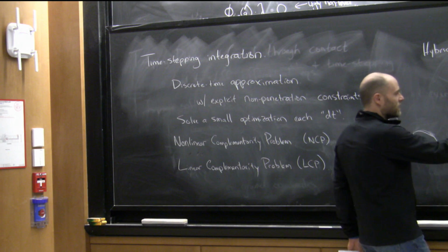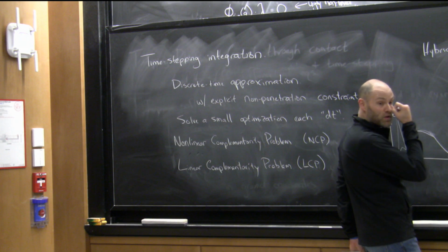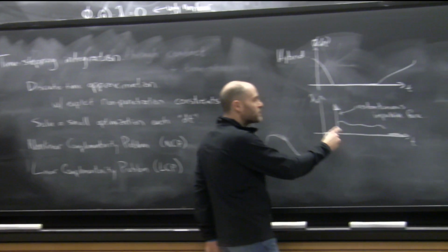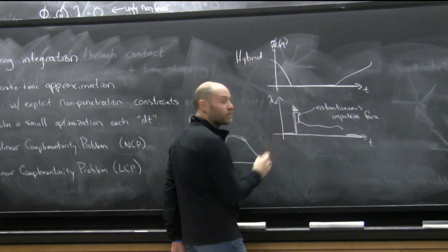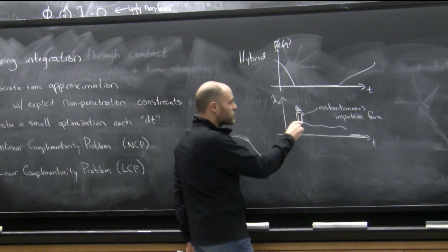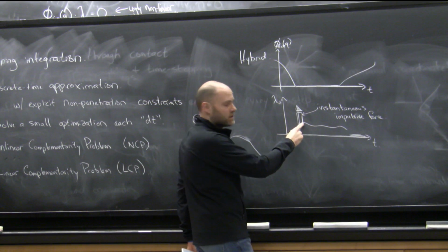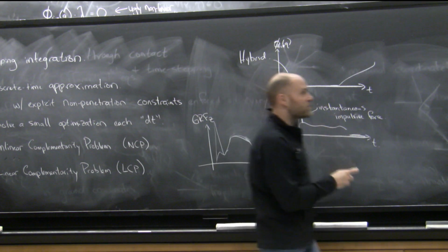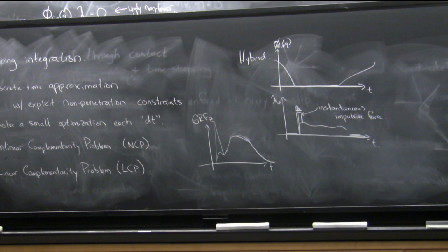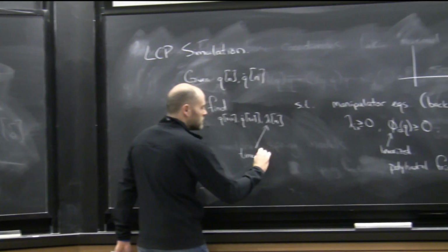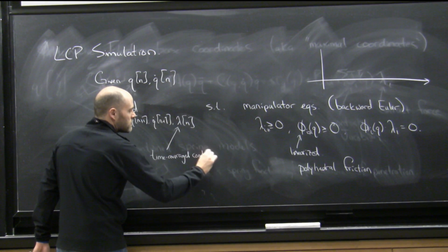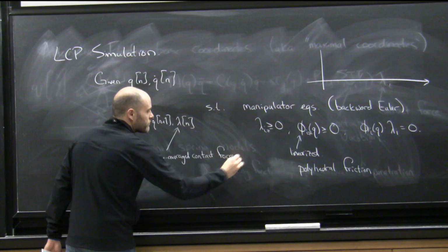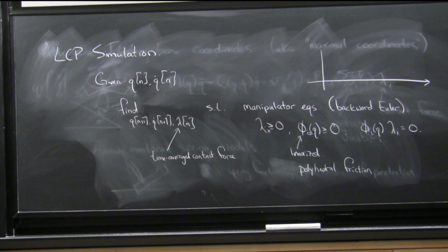Right, so this thing gets spread. The solver, in order to achieve that stopping, will produce whatever force it needs to, which would be a finite time-averaged approximation of that, in order to bring you to rest here. So the forces in this have the interpretation as a time-averaged contact force in the discrete time formulation.